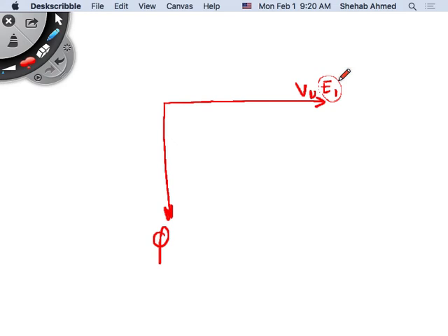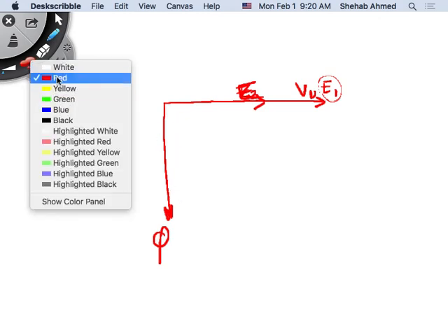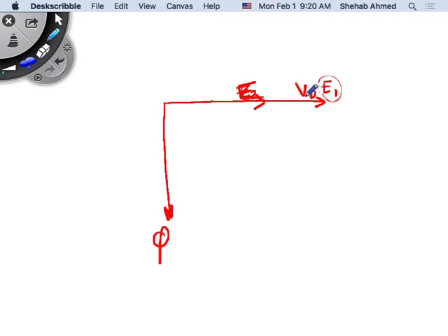Remember, initially I had no back EMF. The transformer does not have a back EMF. You put voltage, it causes current to flow, and this current causes flux to develop. This flux generates a back EMF voltage E1. It also links a coil on the secondary side, generating voltage E2. Now E1 and E2 are not equal because of the number of turns, so this is E2, for example. Let's say it's a step-down transformer. This is my transformer. And of course, this φ1 was generated by a component, because V1 created a current.